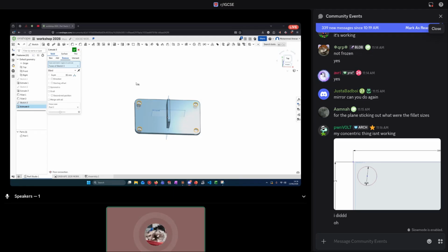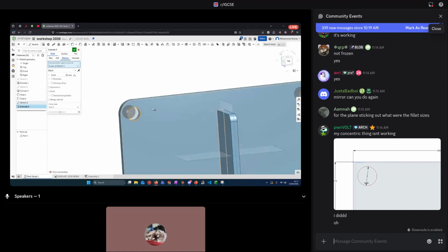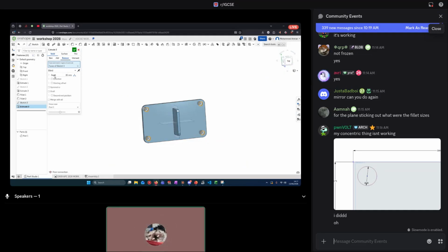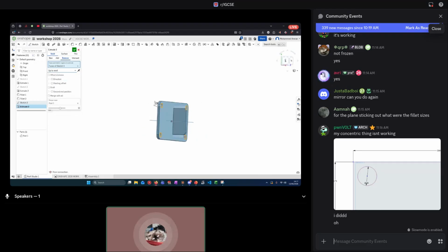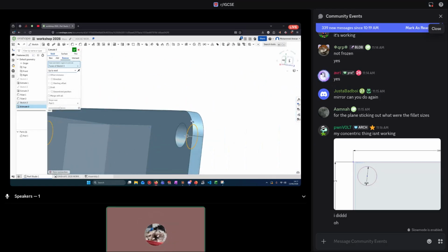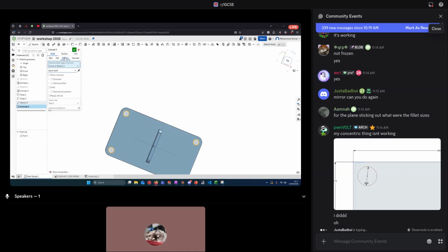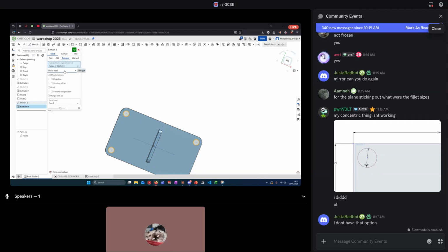Okay, so right now, I'm in extrude. So solid, remove. Before we were adding, we were extruding, like we were adding material. But this time, we're going to remove material to create the hole, as you can see. So after clicking on remove, we're going to make the end condition, the end type, up to next. Up to next means it goes up to the next face. So it's going to go from here, it's going to make the hole until the next face. Okay? So once your options are like mine, remove and up to next, you don't have which option? Up to next?